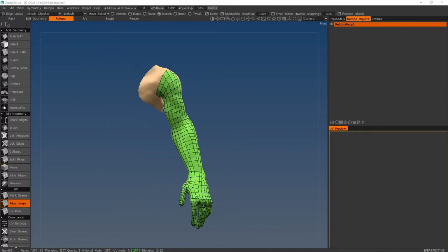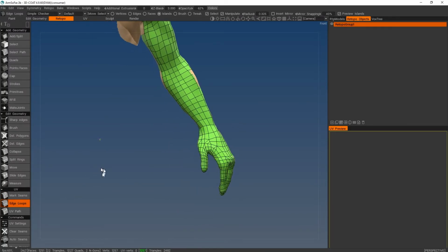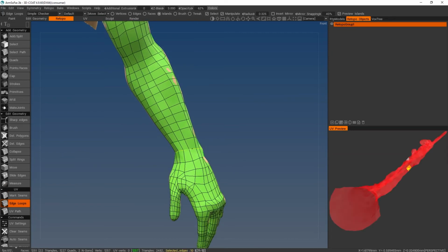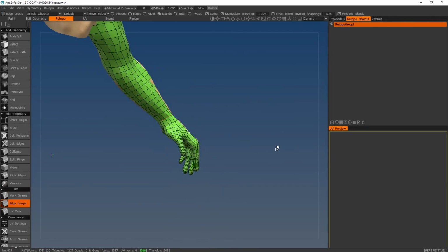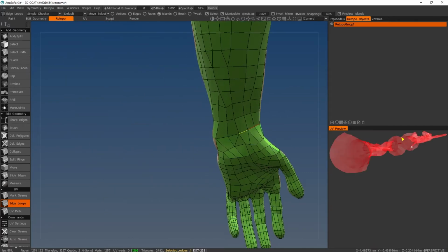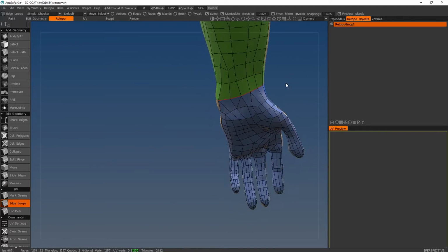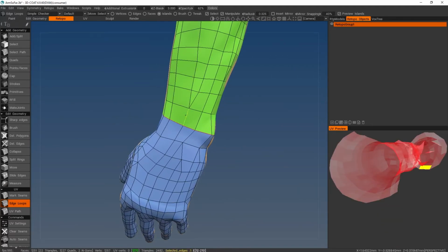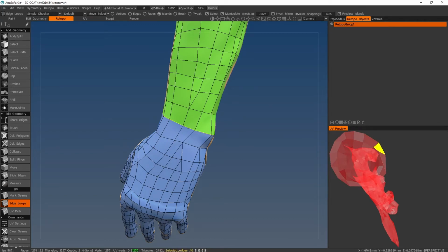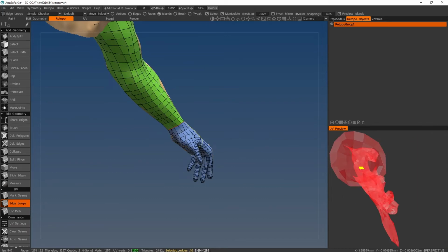So if I look at the retop objects, at this stage we're ready to go in and arc in the seams. So I'm going to use the edge loops for this. If you use edge loops, it will go in and it will select the loop. So if I click this, we can see that it's gone part way around. I haven't quadded here, so it's not connected that. Once you section off an area, you'll see that it will separate away. So I now have two islands.